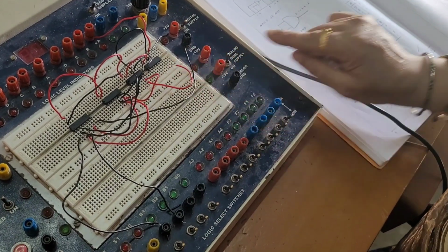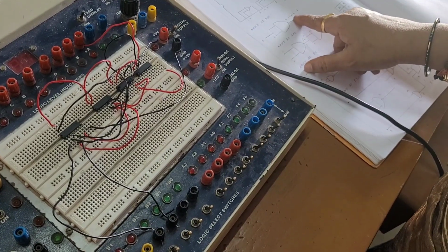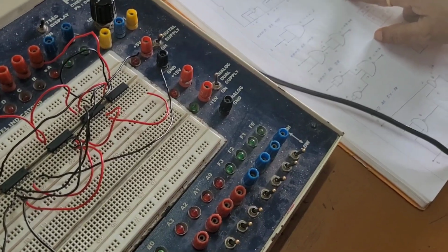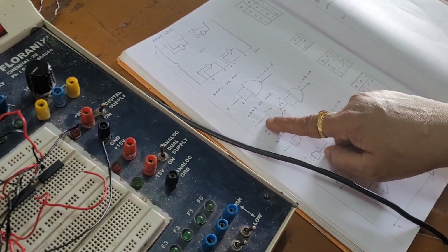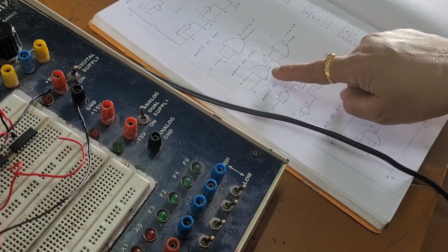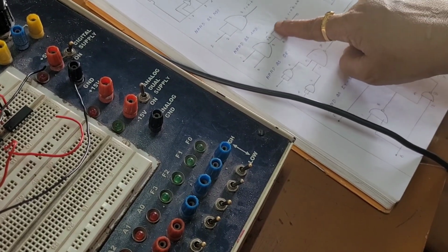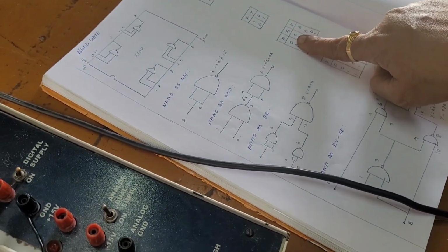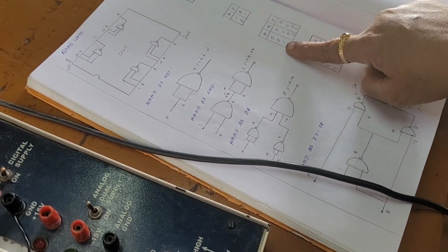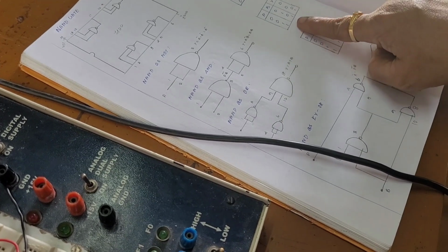Okay, then in A input you are connecting both 1 and 2, and you are getting Y is equal to A dot A bar dot A bar is equal to A bar. So the truth table is given here, and NAND as AND gate. The NAND as AND gate uses 2 NAND gates; you have this NAND gate and this NAND gate, and here it is tied together. You have the truth table A, B and Y. A is equal to 0, B is equal to 0 and Y is equal to 0. And 0, 1 will give you 0, and 1 and 0 will give you 0. 1 and 1 will give you 1.